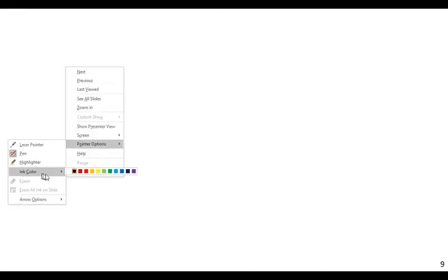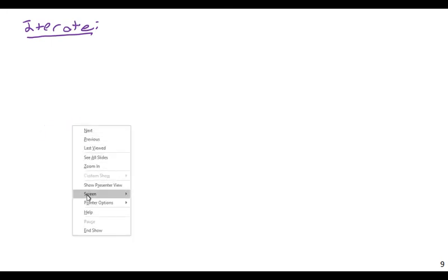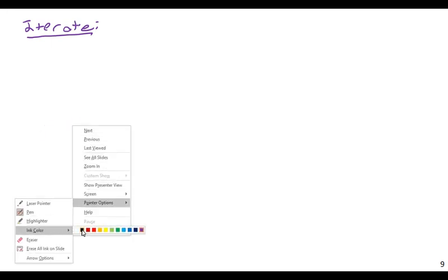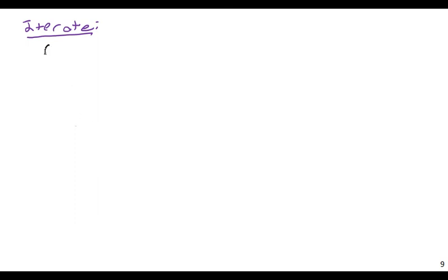Same as before. Iterate. So I'm going to start by assuming the friction factor. Again, I'm going to start by assuming my middle of the road value. Let's assume the friction factor is 0.02, something from the middle of the Moody diagram.